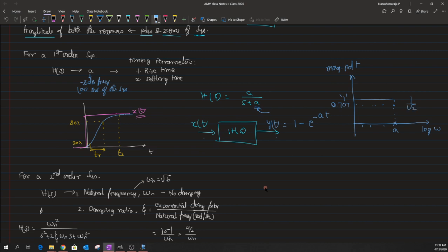So the signal makes a kind of transition that goes something like this, and then it moves at a rate of minus 20 dB per decade. But rather than using this kind of behavior that I have plotted right now, I would use a piecewise approximation, which means that I assume that the gain through the medium stays constant till I reach the first pole, and after that the gain degrades at a rate of minus 20 dB per decade. This is the approximation that we will be following throughout the session.